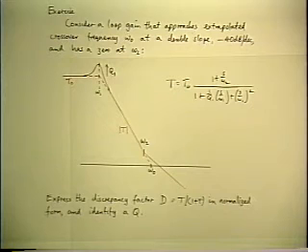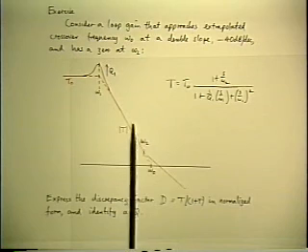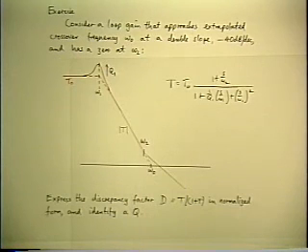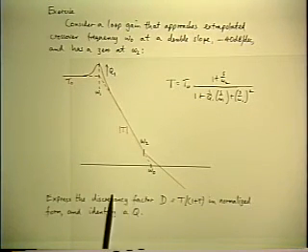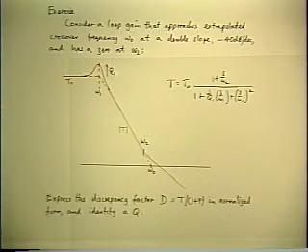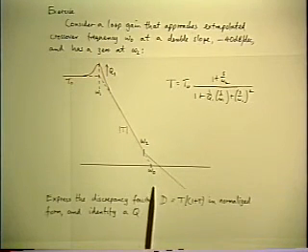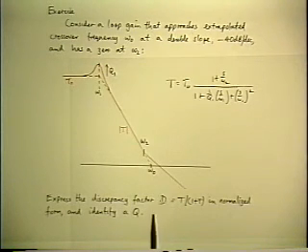And so what I've done is led you up the garden path, because the proper way to start this is simplify the problem before you write anything. And it's exactly the same simplification that I talked about in the previous case, where we had a single pole followed by a second pole further down. And I started off by saying the only part of interest in the solution is what happens near crossover relative to the position of the 0.